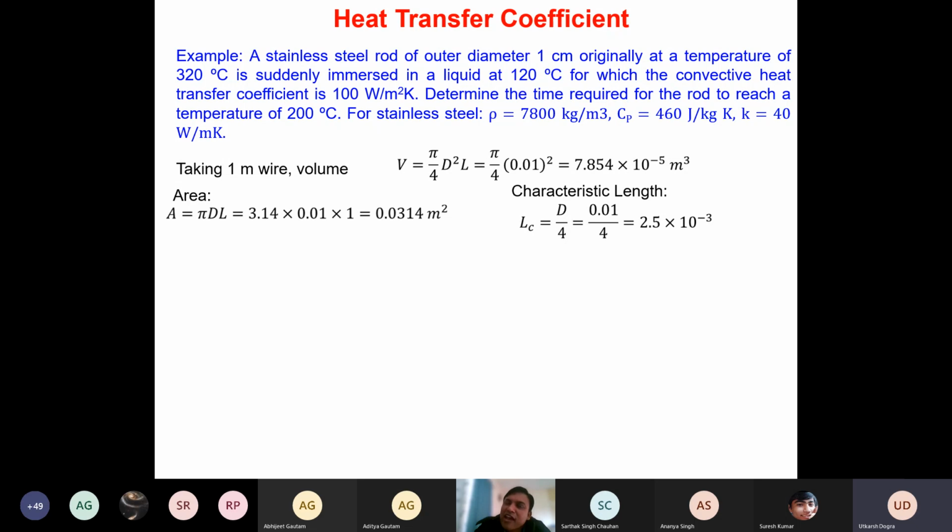Remember, for calculating the drag force, etc., you require the diameter, isn't it? And there you assume that the entire particle is spherical, but very often you do not have a spherical particle, isn't it? So how do you represent non-spherical particles? By using an equivalent diameter, isn't it? Yes or no? Yes. So this characteristic length is similar. Is it clear to everyone?